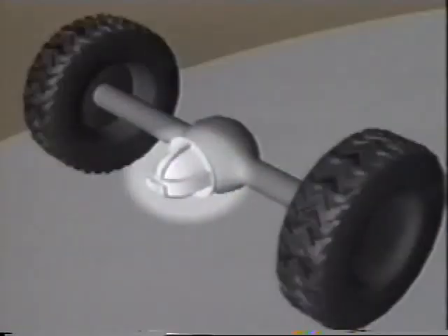Each side gear sits in either end of the differential housing and is splined on their inside diameter to accept the splined ends of the axle shafts. Supporting the pinion drive gear, ring gear, and the differential assembly is the carrier housing. It bolts to the axle housing to complete the assembly.